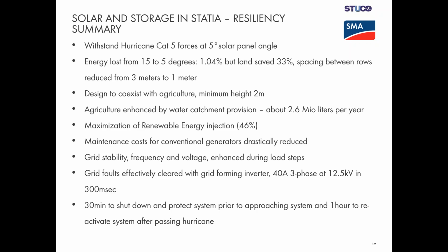We have now achieved a maximum renewable energy injection of 46%. Maintenance costs of the generators are of course drastically reduced because the running time has been drastically reduced and we go to diesel off mode.